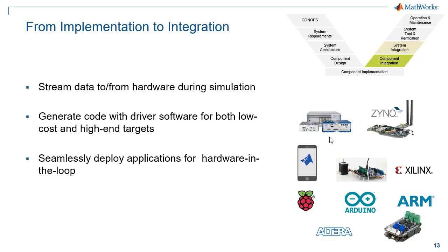So Simulink Real-Time is the case where you want to take aspects of your model, generate code for them and run that code in hard real time, but you still want to be able to make tweaks or evaluate how things are playing out from your Simulink environment. That is what Simulink Real-Time specializes in doing. It has the ability to target C code and HDL code for FPGAs onto these SpeedGoat boxes here. So check that out if you're interested in rapid prototypes or hardware-in-the-loop simulations.